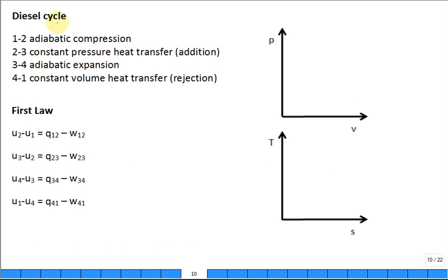Did we sketch out the diesel cycle on the PV and TS diagram? We did? Let's go 1, 2, 3, 4. 1, 2, 3, 4. If you have the heat addition right here, Q_in, that's Q2 to 3. That's going to be a C sub P, T3 minus T2.